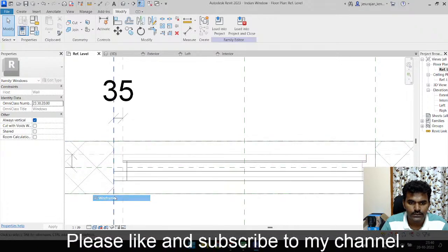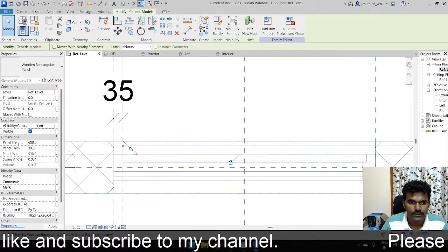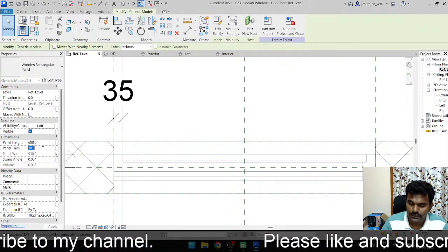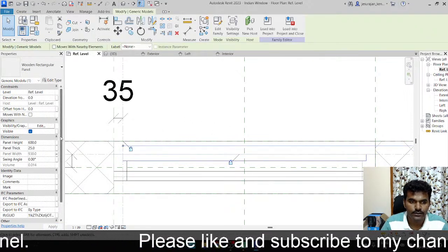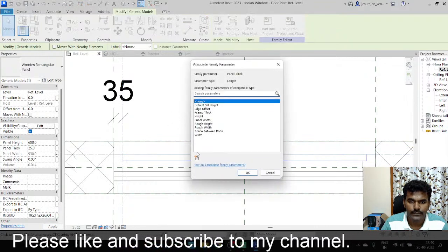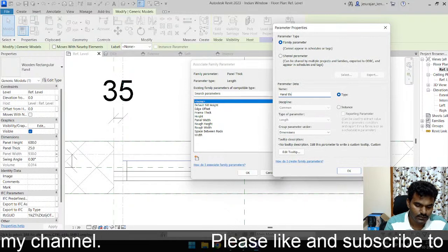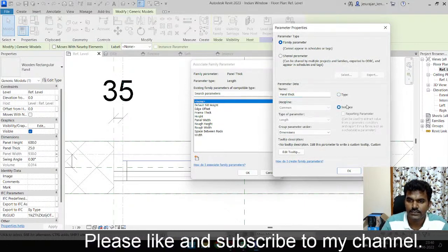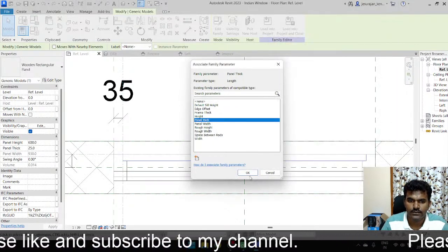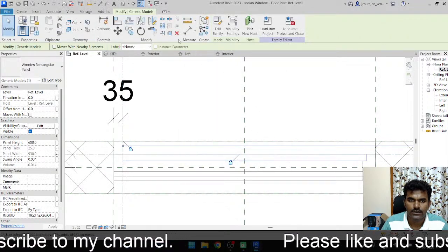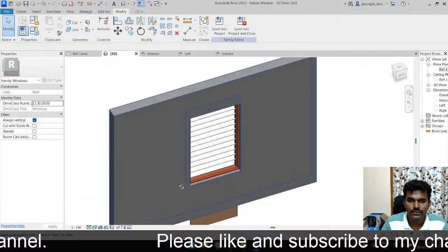Keep this as wireframe. What's the panel thick? Keep this as 25. Create a parameter called panel thick, instance. Okay, now you see how this looks.